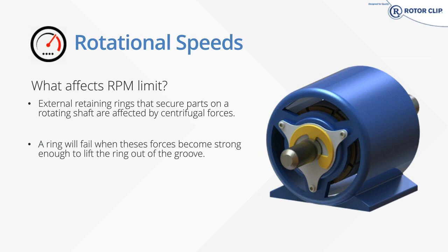We have reinforced versions of our rings, which we'll see later in the load section, but basically we have our standard radially installed E-ring, and if you require additional rotation speeds or additional loads, we have our RE style ring, which you actually see pictured on this slide in gold. Likewise, our SH shaft rings have a reinforced version, the SHR rings.